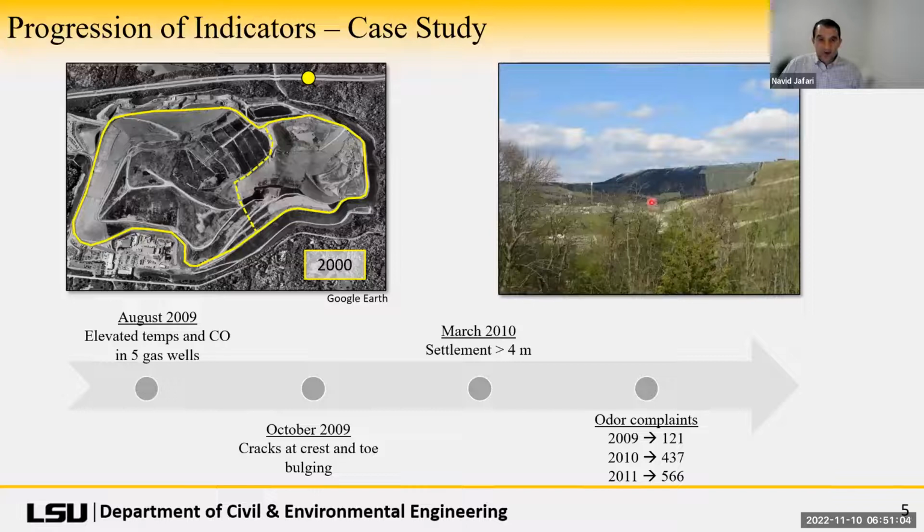And this is a photo that I took circa 2014 or 2015, and I was located here on the highway looking at this specific cross section. So in one regard, we're looking at the normal landfill, which is pretty much right here. So not disturbed, that's what the elevation on the landfill is. And then as you translate from unimpacted to impacted, you can see the stark contrast in elevation on the landfill, showing that the ETLF has been ongoing for quite a while. So that was the settlement starting in March 2010 or prior to 2010.